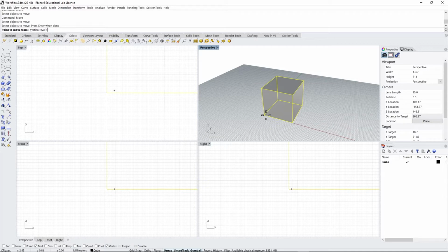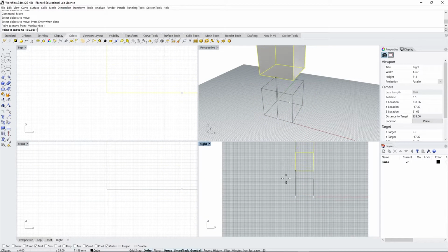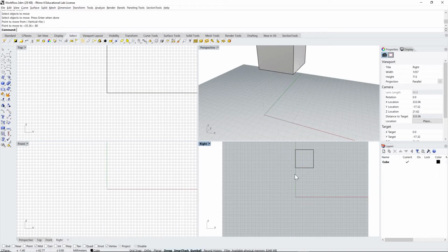We can also do this by typing move and then selecting the object, enter, and we can grab our object from one location, and we can press Shift. By pressing Shift we can lock the directionality, so this can be in the X direction or Y. So we can also change to lateral view, and then we can keep the Shift, and we can define a certain distance by typing first a distance, then pressing Shift and enter.